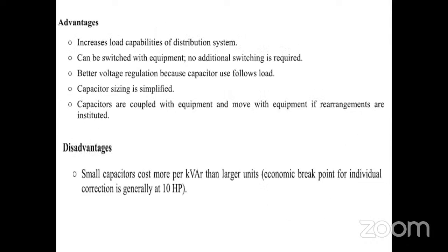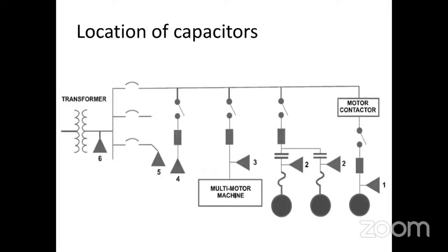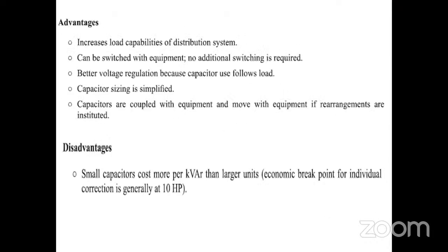Increases the load capabilities of the distribution system, and can be switched on with the equipment. In this case, the capacitors are connected near the load. That means there is a motor, and the motor will be fitted with one capacitor.